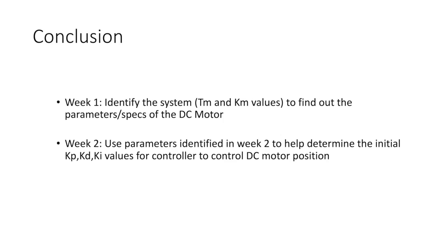From the experimental data, it was seen that an added mass increases values for angular velocity at steady state and thus the motor gain, or Km. This will later be useful when trying to make the PD controller that will ultimately be used by Quanser Incorporated to have its DC motor move to the desired position autonomously without human intervention or input.